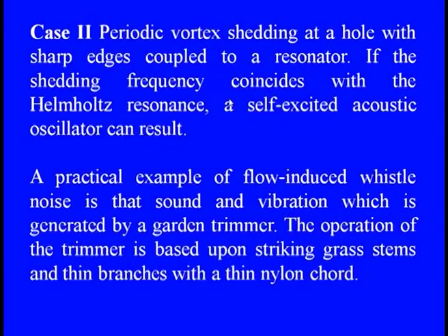And in the second case, we can take the periodic vortex shedding at a hole, when it is passing the sharp edges, it can go straight into resonant conditions. If the shedding frequency coincides with the Helmholtz resonances, as I showed in the previous case, certainly we have the resonant condition and a huge amount of vibration is generated.